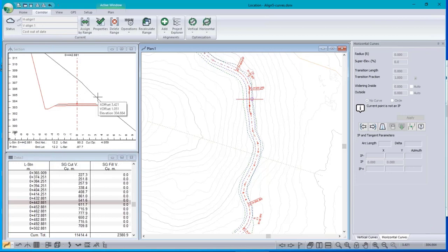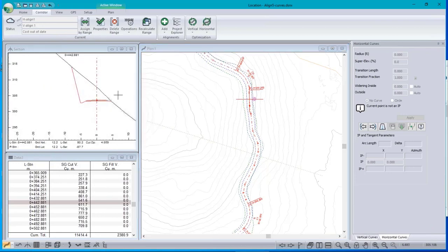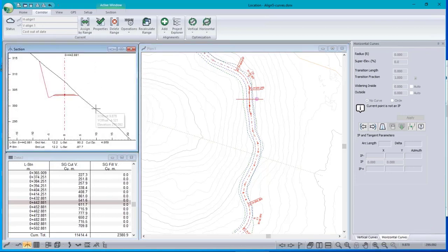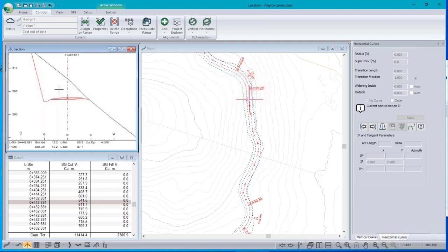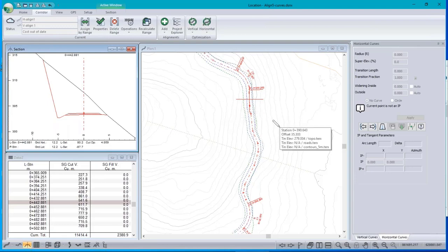And so you don't fill because it rattles down the slope and looks ugly and destroys the environment. And then you have to truck the material out. And they call that an end haul road because the material that you're cutting has to be hauled out to the end where they dispose of it in a spoil site somewhere or use it to build something else.